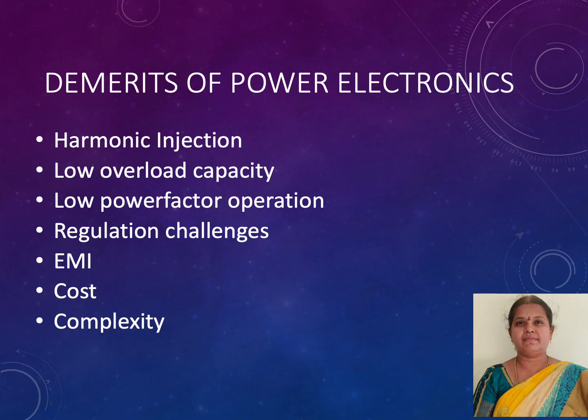Even though we say power electronics plays a major role in all aspects of electrical engineering, it has its own demerits like harmonic injections, low overload capacity, lagging power factor operation, regulation challenges and EMI, electromagnetic interference issues. The cost involved is more due to the introduction of converter circuit and control circuit, and complexity is also increased due to the control circuitry.